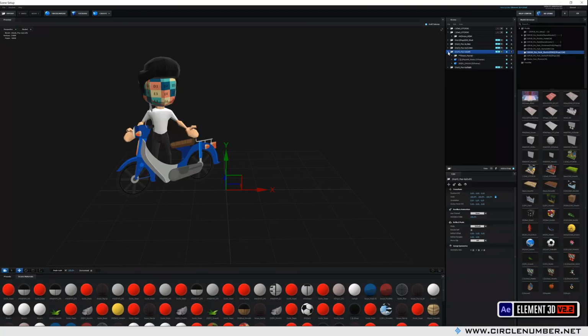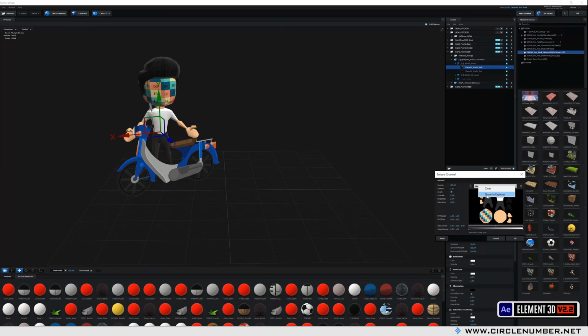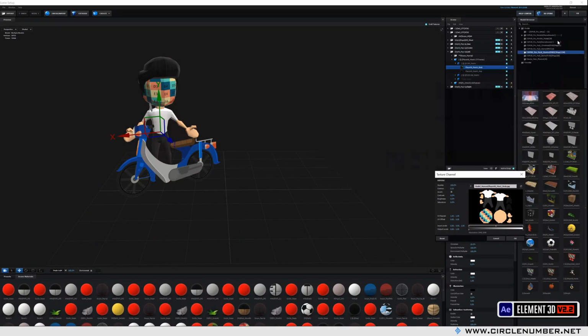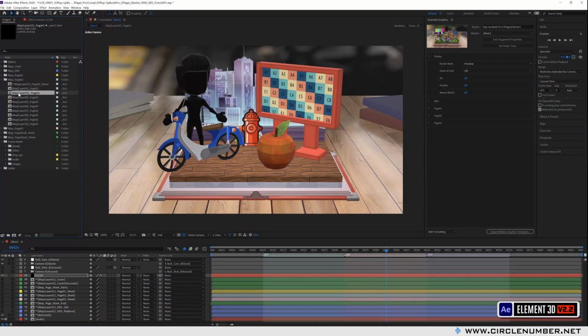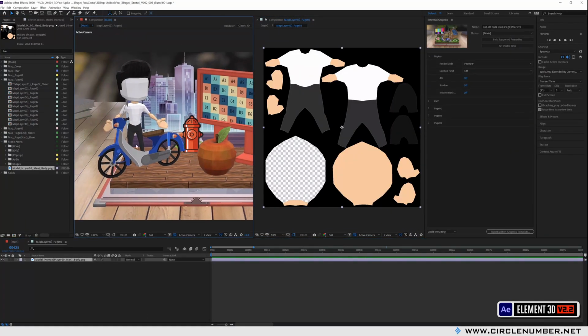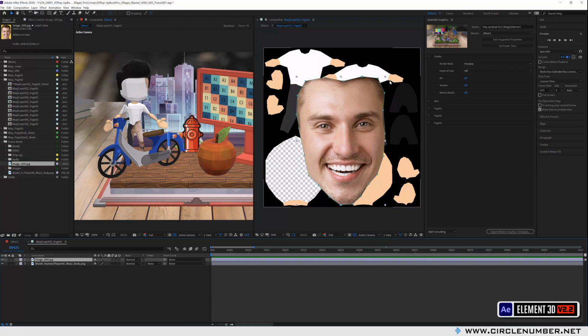You can add a face image to a 3D character the same way you would apply an image to any 3D object. Open the Characters Texture folder, locate the diffuse map, and replace it with the custom layer you want to use. Go to the layer you selected for the map, choose the character image from the Character Texture folder, and add it to that layer. You'll then have a 3D character ready with the face applied. Select the face image you want to use in the layer map, mask the face and position it correctly on the character's face. Then, set the background to a skin tone that matches the character.